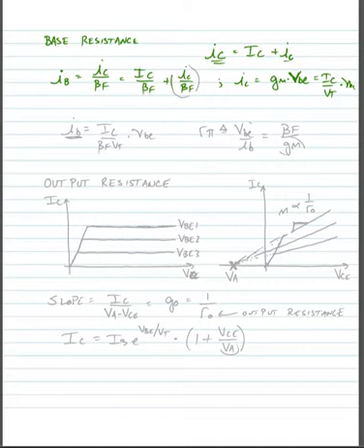Substituting back in and just selecting the small signal term, that is the AC term only, we can write that little ib is equal to IC over beta forward VT times vbe. Now we define the base resistance, r pi, as equaling vbe divided by ib. So we can find that r pi is equal to beta forward over gm. Interestingly, this only depends upon the bias current and the temperature, as gm only depends on bias current and temperature.